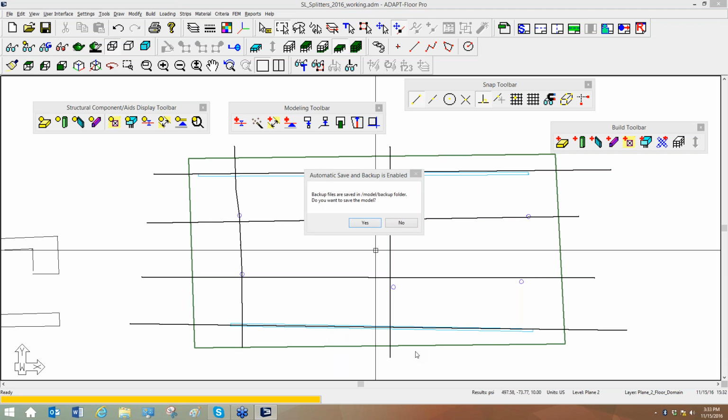So when we do release the ability to do ramp slabs, it would only be available in the RC module versus PT, because we have to work out from an architectural standpoint, program architecture, how we can use tendons that reference a slab which is being sloped, and it has to do with how the tendons are being offset to a reference plane or an analytical plane, and some nuances in that respect.